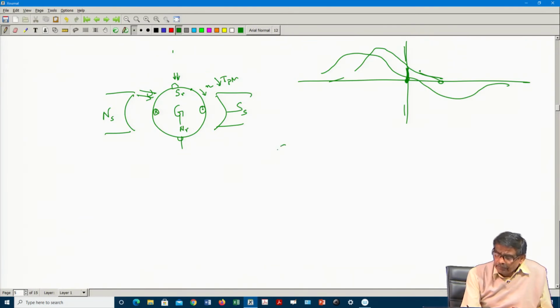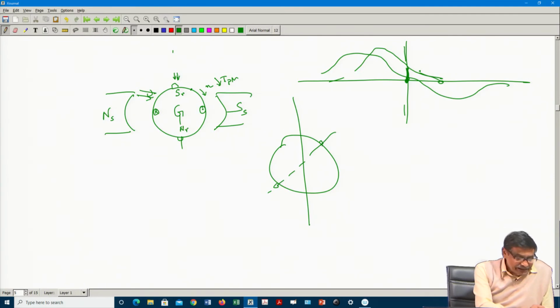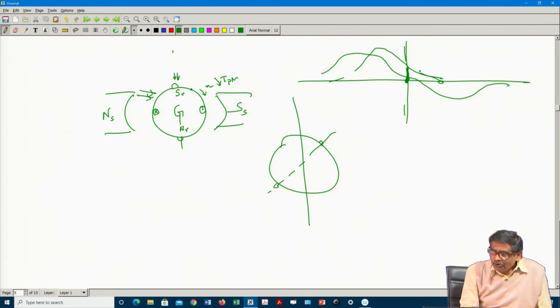So, sometimes people make a slight brush shift here. The question was asked, how do you know where it is 0? Yes, it will not be exact, but it will improve commutation, because 0 will take place here.